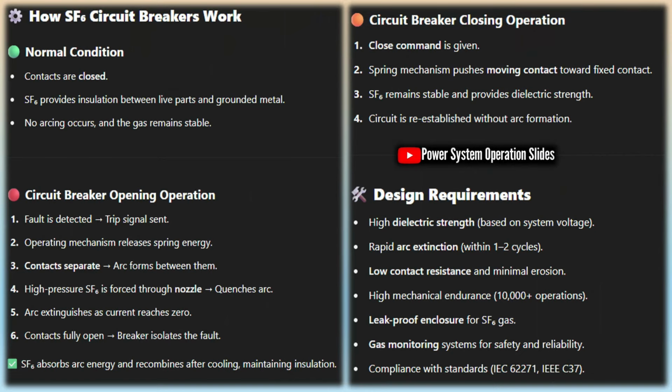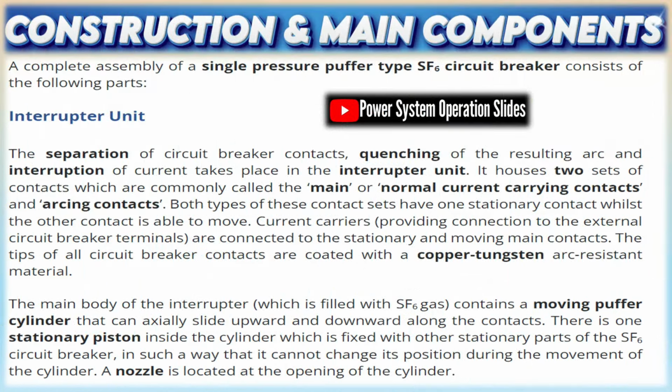For transmission line switching applications, these circuit breakers may be equipped with pre-insertion resistors (PIR) to dampen high magnitudes of switching transient overvoltages. These PIRs, normally 300 to 600 ohms, are connected in parallel with the CB main contacts. They are inserted in the circuit for a specified time interval, 8 to 12 milliseconds, before main breaker contacts are closed. Different configurations of SF6 circuit breaker: the external connecting terminals are fitted with grading rings to ensure that the electric field stresses at the terminal surface do not exceed corona onset.